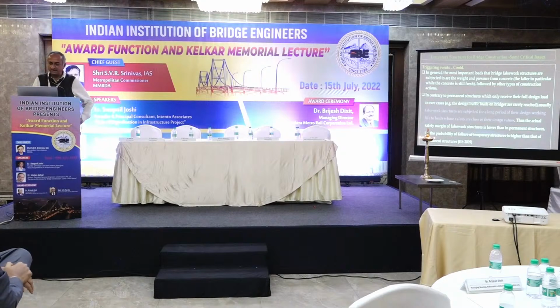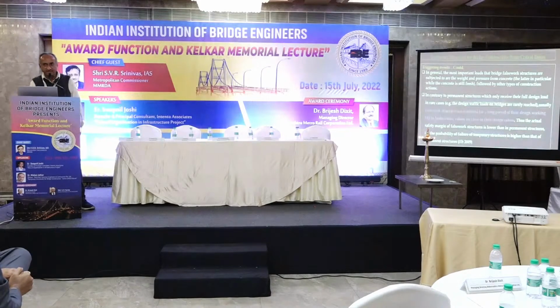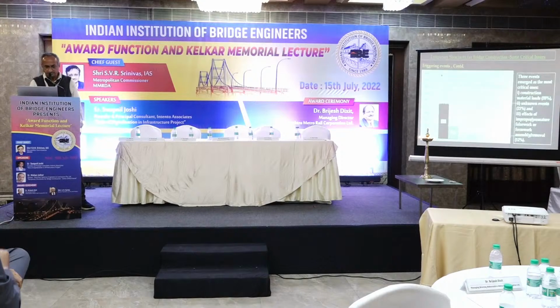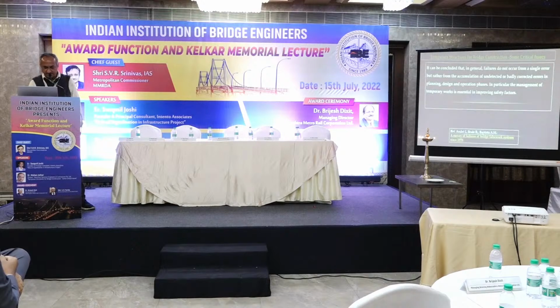Triggering events in general are important loads that bridge falsework structures are subjected to from the concrete, and this is the most important reason. Contrary to permanent structure works, which may be subjected to some hypothetical loading only once in a lifetime or a few times in a lifetime, the temporary structures are loaded most of the time to the design loads for which they are designed, and so the possibility of failure of temporary structures is higher than permanent structures. So I'll just skip this.